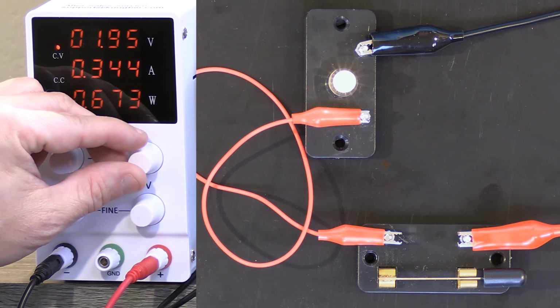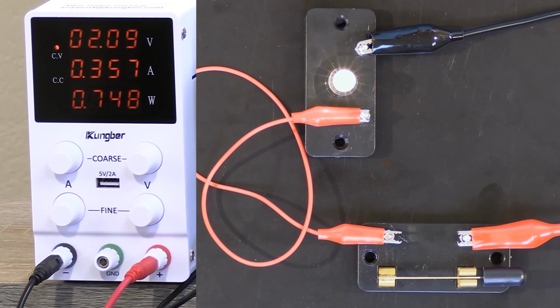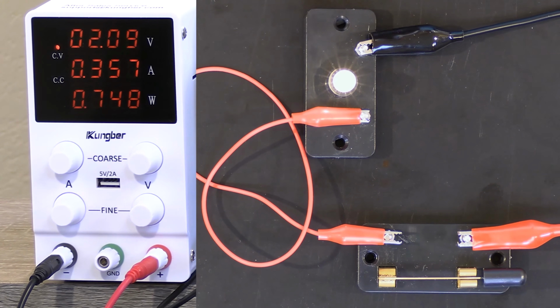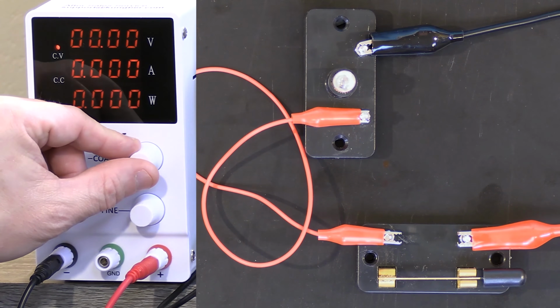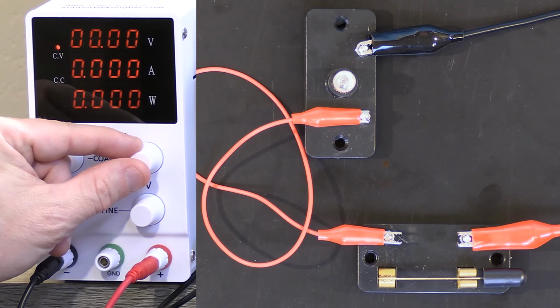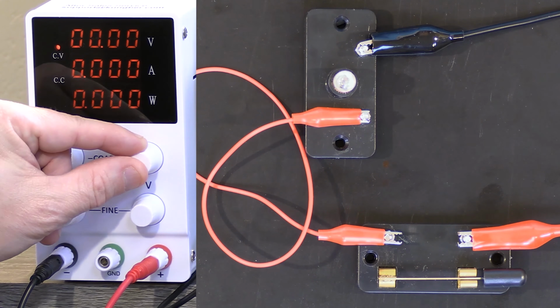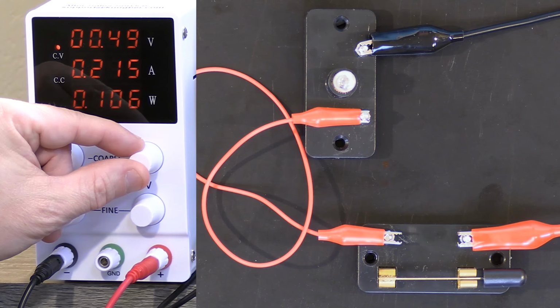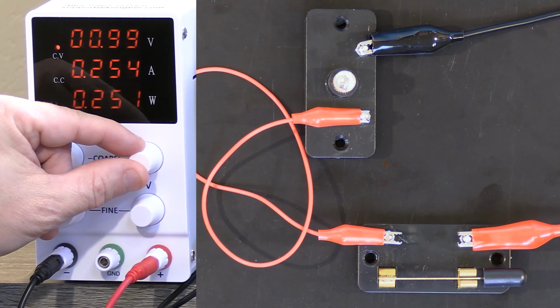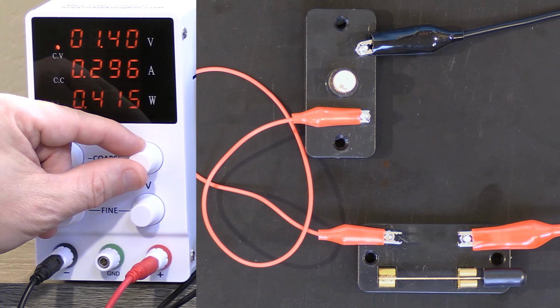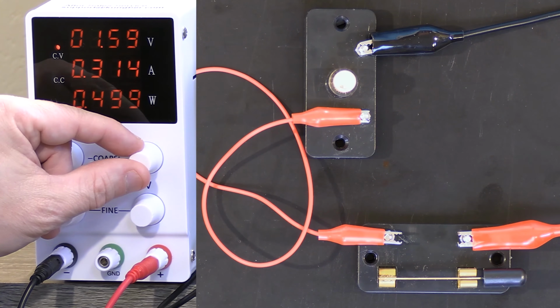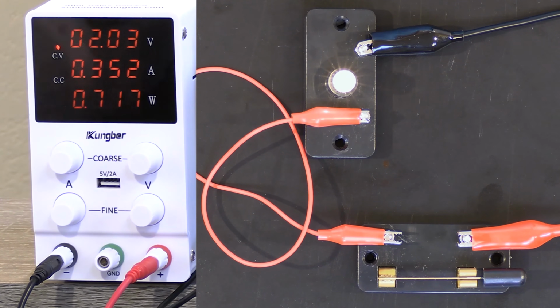Now, if I increase this higher, to 2 volts, notice it's awfully bright. If I increase it too much, the light bulb will just get so hot it'll burn out, right? So that can obviously happen. I want to do it one more time and sweep, and I want you to focus on these numbers as I smoothly go to 2 volts. Notice how, as I slowly increase the voltage, the push is increasing, and that's causing the current to increase. It's also causing the power in watts, which we'll talk about later, to increase as well. Voltage is push. It causes current flow.